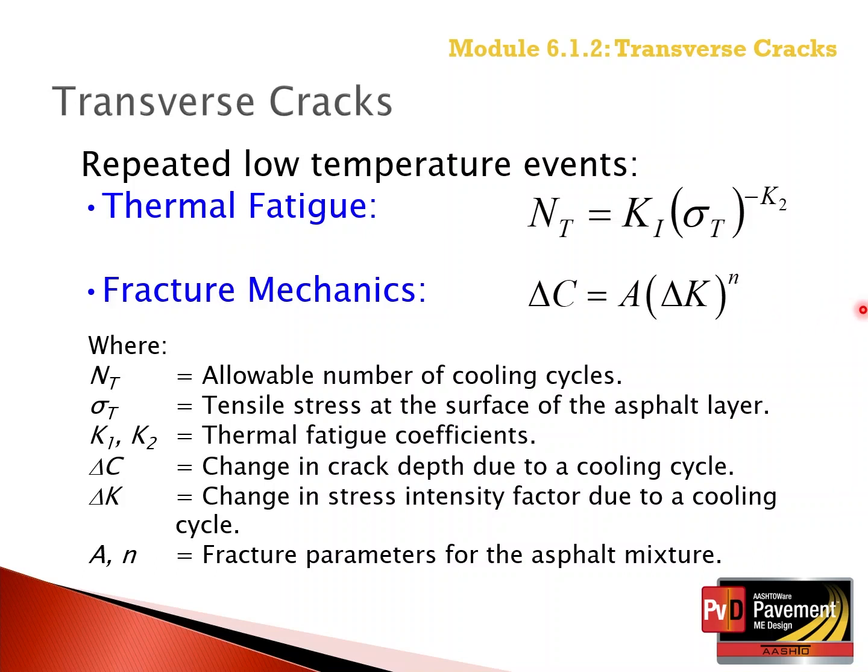Earlier versions of the software used the thermal fatigue to determine when the crack initiated at the surface, but used fracture mechanics to determine the time of when the cracks propagated through the asphalt layer. The more recent version of the software uses or relies on the fracture mechanics approach in predicting both crack initiation and crack propagation.